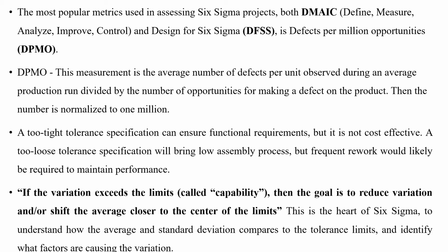Suppose your tolerance is too tight for the functional requirements, it will not be cost effective. A tolerance that is too low also brings a low assembly process, and again we have to do rework to maintain performance. That's why we have to maintain these tolerance limits based on your process.